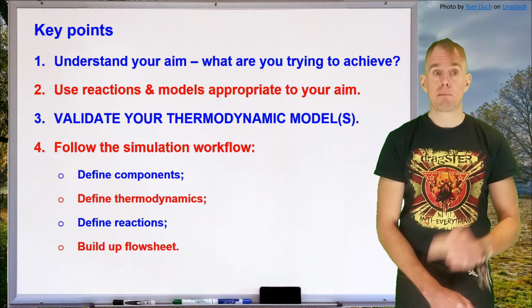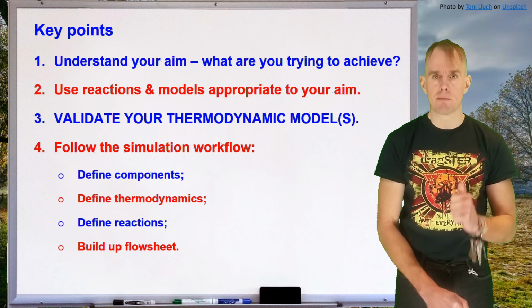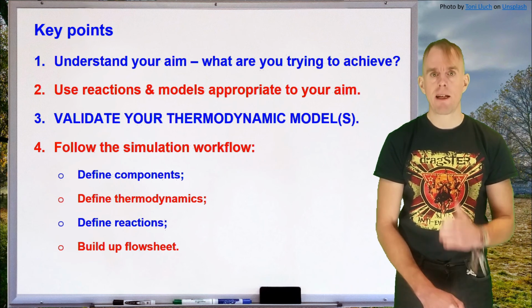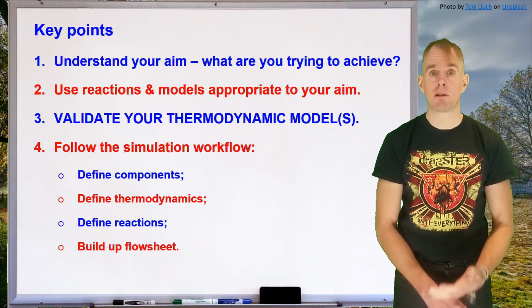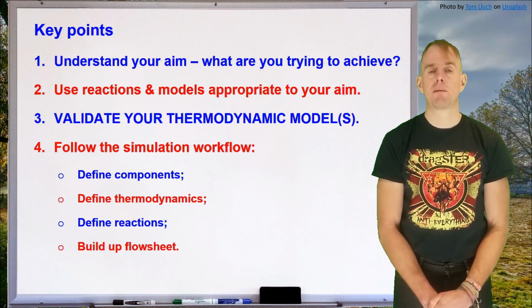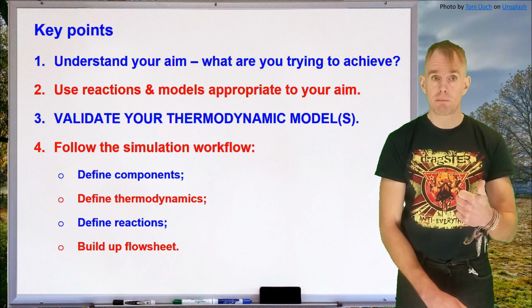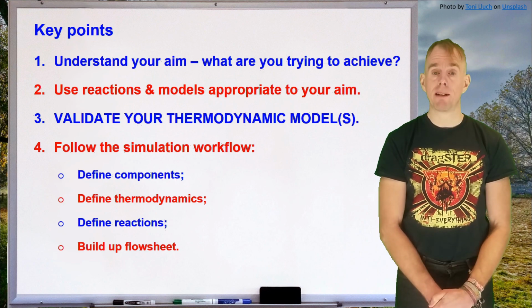Third, really importantly, validate your thermodynamic model. An unvalidated thermodynamic model can wreck a simulation and render all the hard work and time that you've invested in making it absolutely pointless. Fourth, don't forget to follow the simulation workflow. Define your components, define the thermodynamics, define the reactions, and then build up your flow sheet.